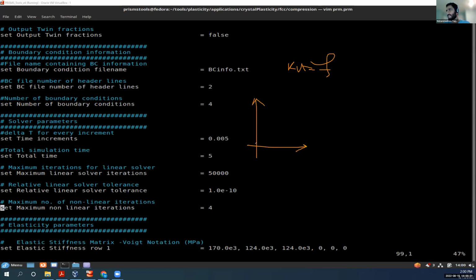So your curve is like this. It's different from a linear material, where your load curve is like this and you can basically do the whole simulation in one step. What you need to do is define some sub increments for each loading step, and then solve this by the famous Newton-Raphson method. It requires a certain number of iterations for each increment of these load steps. This defines the number of nonlinear or Newton-Raphson iterations for each load step.